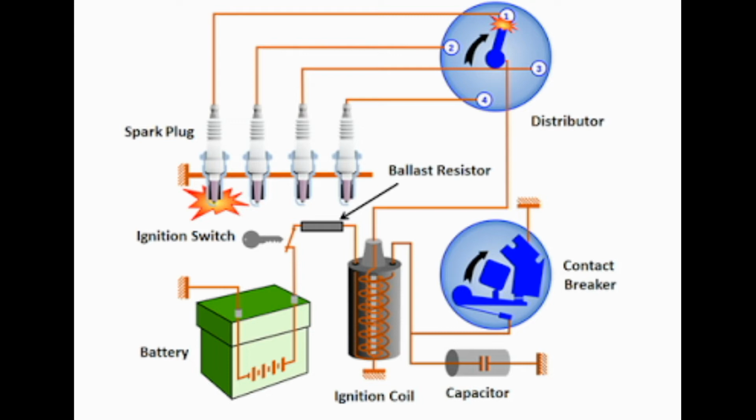The pivoted arm generally has a heel or rounded part, the cam follower, made up of some plastic material and attached in the middle of the arm. The heel rests on the cam driven by the engine. Every time the cam passes under the heel, the contact points are forced apart and the circuit is broken. The pivoted arm is spring-loaded, and when the points are not separated by the cam, it is held together by the spring force and closes the primary circuit. When the points are closed, the current flows through the primary circuit, and it stops if open.